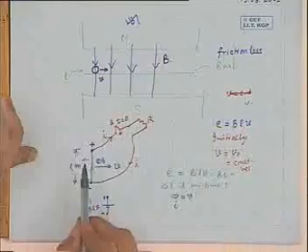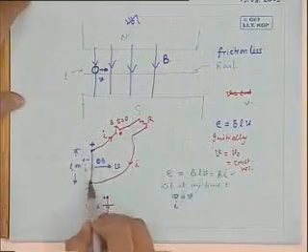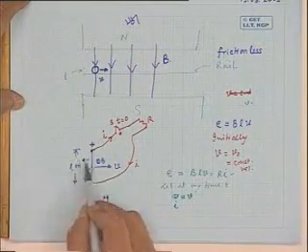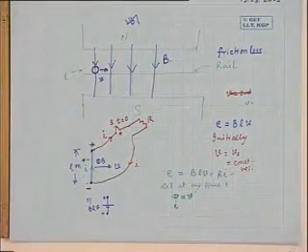The magnitude of that force will be B into I into L, because they are mutually perpendicular, and you have to apply the left hand rule there. This is B, perpendicular into the paper, I is like this. So it will experience a force in this direction. Therefore, the conductor will experience a force in a direction opposite to its motion.